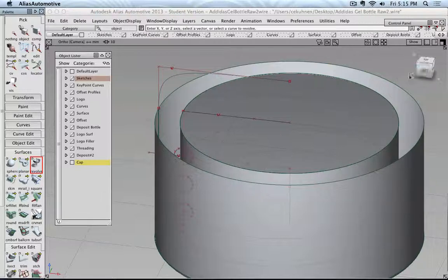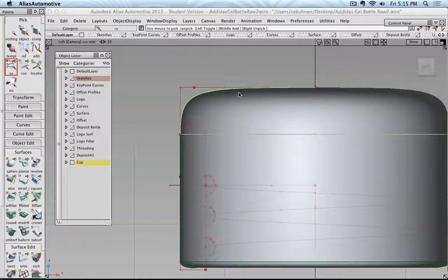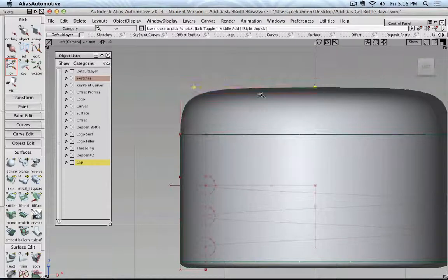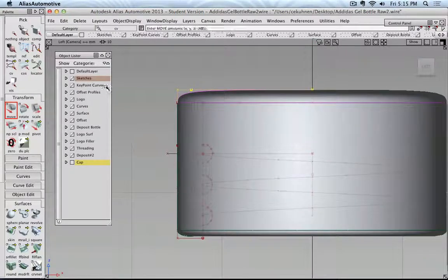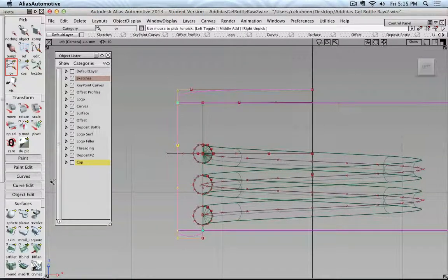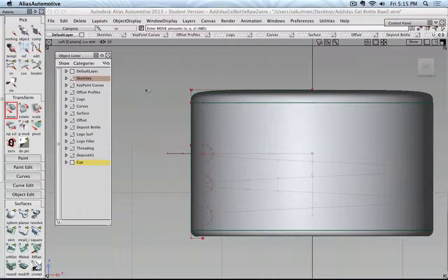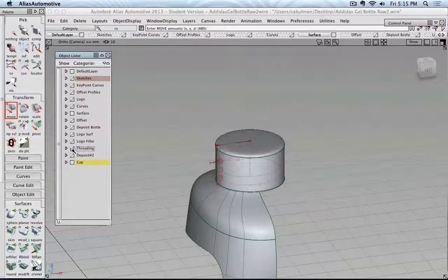Okay. And then the last part up here, our massive cap with way too much material. And because of that, I'm going to select those points and just lower them a little bit because the cap is way too thick there. Maybe like this, okay. And I would like to do the same also for here. And just middle mouse button, move it over, maybe to there. Yeah, that looks better now. Okay. And then let's take a look how everything looks like.